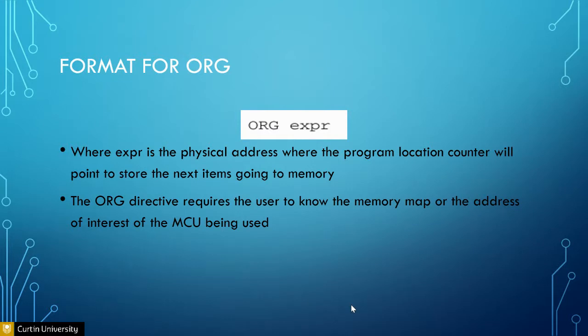The ORG means the origin. You can define where the physical address of your program location will be stored. So if you know that your program's instruction set starts at this memory, you can origin it at a very specific location of the memory.